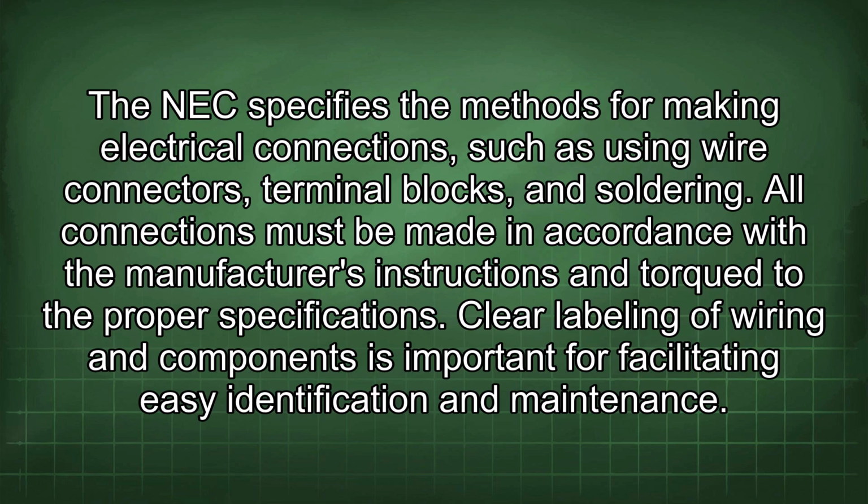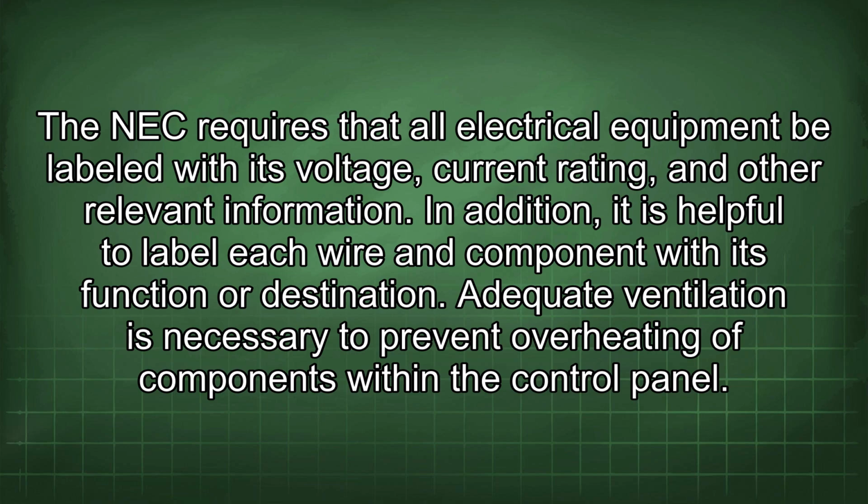Clear labeling of wiring and components is important for facilitating easy identification and maintenance. The NEC requires that all electrical equipment be labeled with its voltage, current rating, and other relevant information. In addition, it is helpful to label each wire and component with its function or destination.